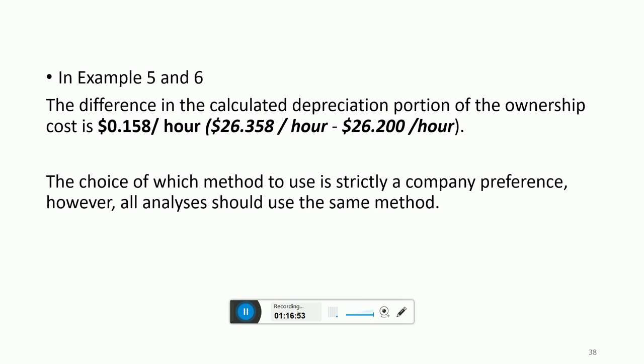A piece of equipment has basically two lives: a physically limited working life and a cost limited economic life. The first is until when the equipment can work properly. The second is cost limited economic life, where the equipment is able to work, however it is not able to work economically. So we have to see both things. Maybe it is working economically, but it is not able to work physically in a good manner, or in a more productive manner.